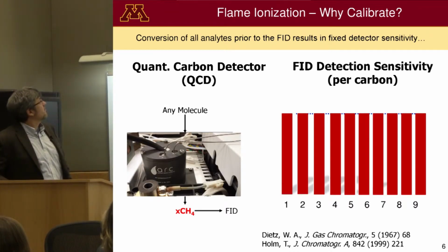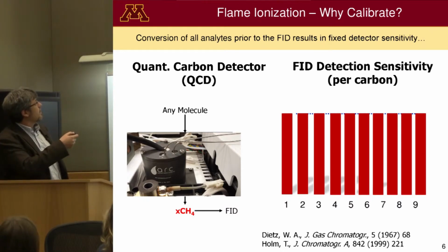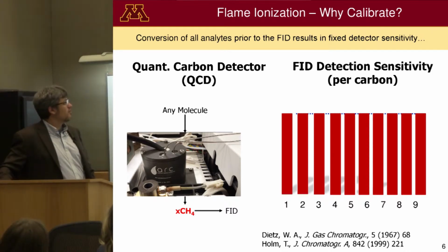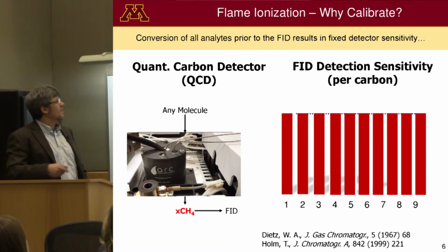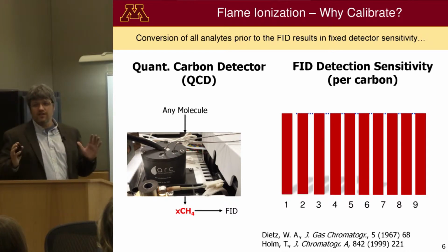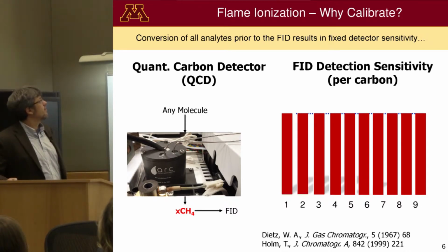And the idea is very simple, right? Could we take whatever molecule analyte we're working with, put it through some sort of inline catalytic reactor, convert everything to the exact same compound, in this case methane, and then just run methane through your FID? Because then every species has the same response because it is the same species. And then of course, all those 9 compounds would all look the same in terms of quantification. So, incredibly simple concept. So how do we do this?